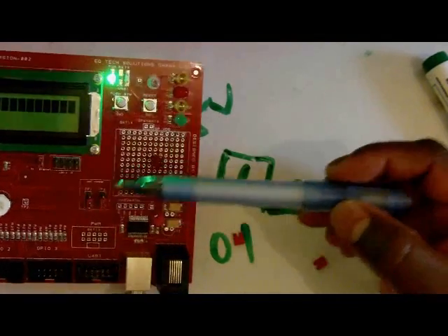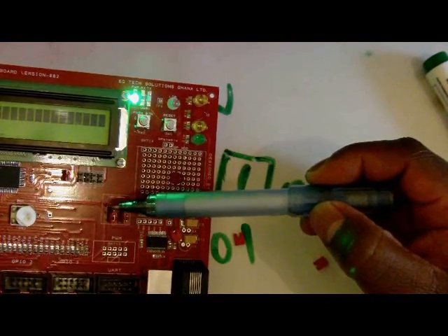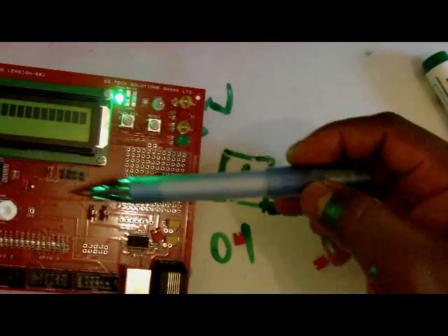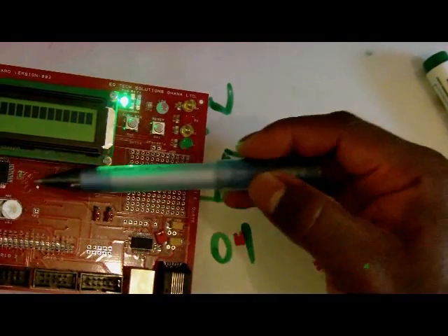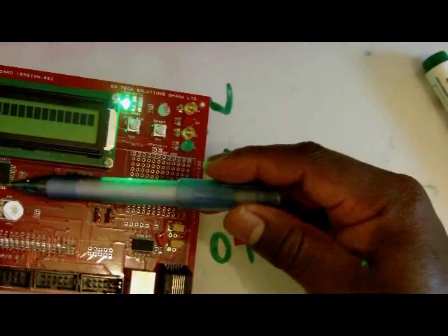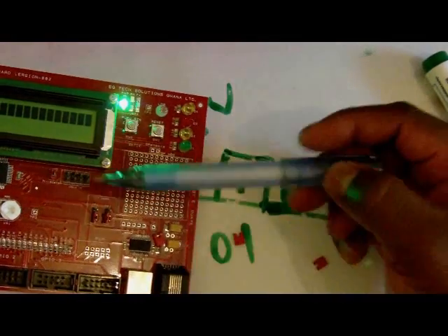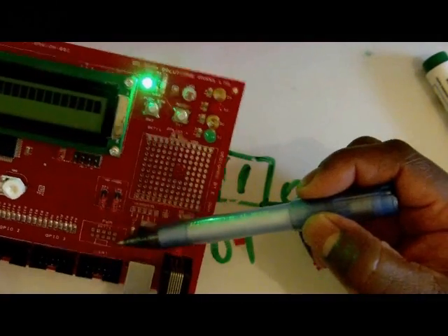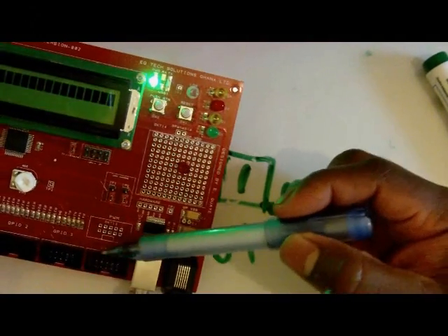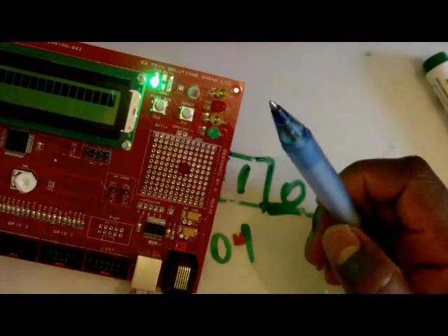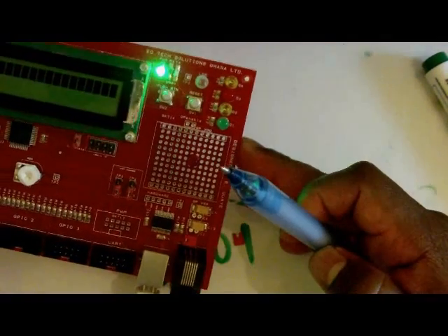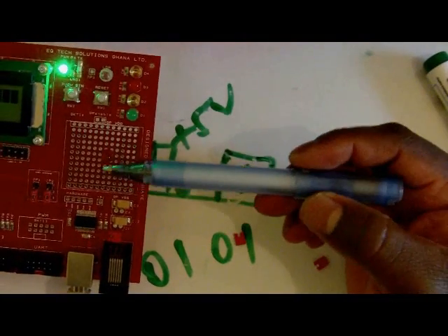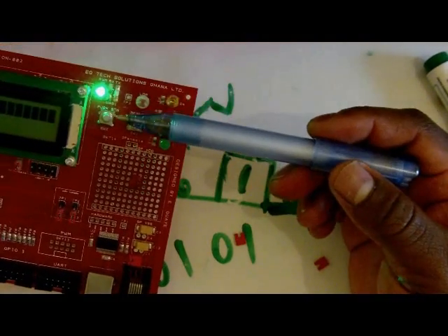Now if I put this jumper on pin 1 and 2, that means I have freed the communication links between the microcontroller and the PC, and I can go ahead and use the UART here, which is written here. I can go ahead and use this socket to drive anything that I want to drive, which requires UART. Okay, all right. Now I think basically I've talked about everything here.